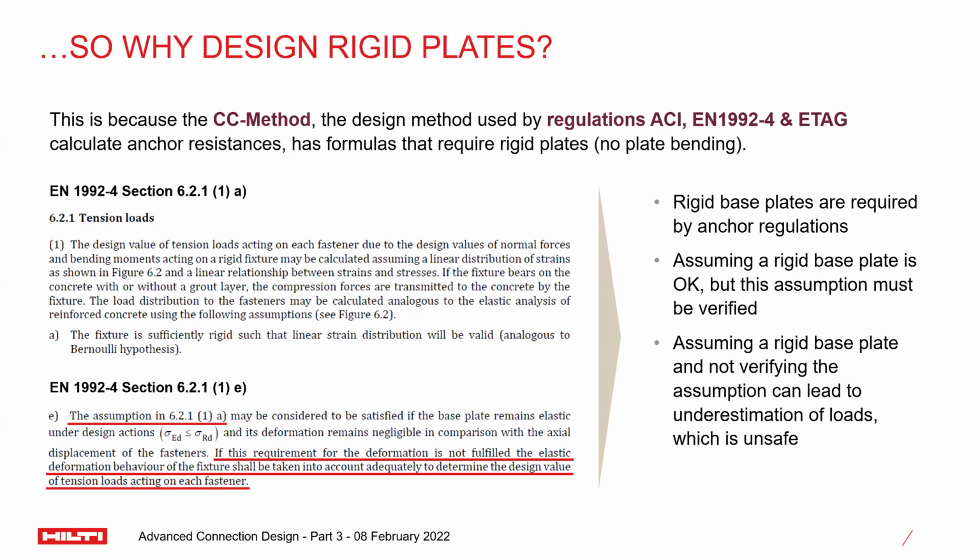So why design rigid base plates? We design them because the regulation tells us to design rigid base plates based on the concrete capacity method. Assuming a rigid base plate is completely okay, but this assumption must be verified, which we will cover in the upcoming section. Assuming a rigid base plate and not verifying the assumption can lead to underestimation of loads, which you would guess is unsafe.